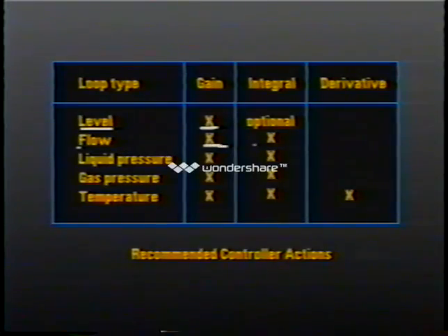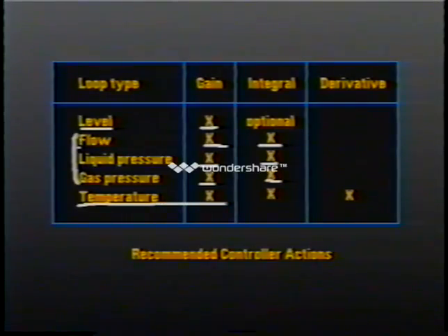Proportional plus integral, or PI control, is the most common type of control because the two modes combine to permit tighter control of a loop and faster response to changes or errors. PID control uses the combined proportional, integral, and derivative modes to control slow, low noise temperature loops.